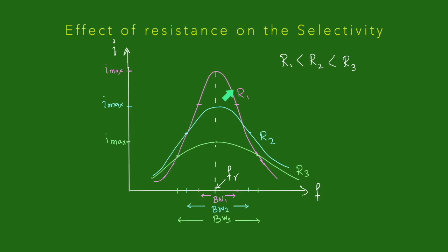Sharpness of the resonance curve indicates that as the frequency of the input signal changes from the resonant value, current in the circuit will drop faster. The LCR circuit is used as a tuning device in radio sets or TV sets. In these sets, we need to tune to a particular frequency, the broadcasting at which is of our interest.